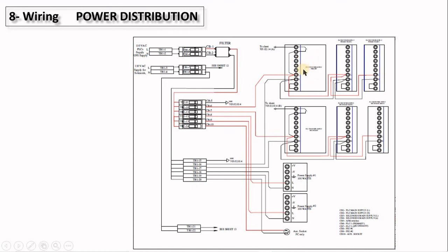So the main benefit of this drawing over the one we have seen is that you now see the actual layout of your PLC, and you know exactly where you're going to connect it. So physically, you know this is 1, 2, 3, the 4th screw from the bottom, I'm going to connect it here. Again, your neutral is separated, and this is one way of showing the drawing. Again, maybe it's a little bit hard to draw, it will consume more time than the previous one, but it's for the guy who is going to do the panel. It will maybe give him a little bit more information.